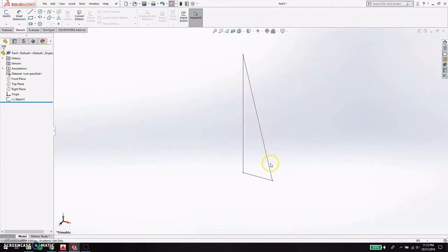So, all right. Now, I know that I'm going to need to form a rectangle that's basically in this line here. And the way that I'm going to do that is I'm going to make a new plane, because I have those 3 planes that I can choose from, but none of those are going to be parallel to this. So I'm going to make a plane that is parallel to this. And you can make a plane a bunch of different ways, but the easiest way for me is to choose 2 lines and make sure that both lines are in the plane. As long as the lines aren't collinear, then you've got a plane.